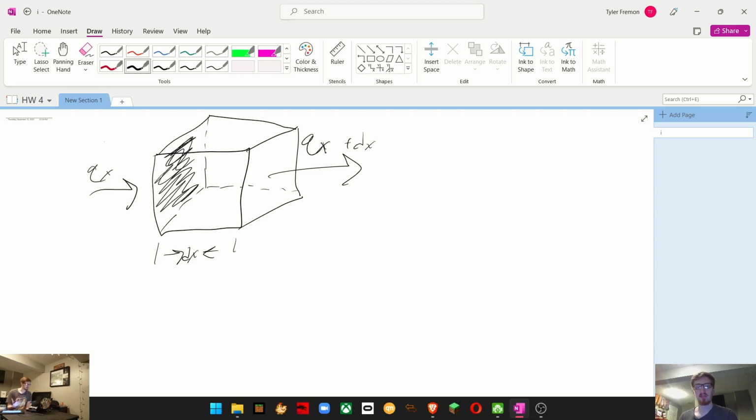And since our goal is to derive an expression for the overall heat diffusion and how we can plug in things that may change the temperature within the control volume, such as a reaction or energy being stored or removed, we can go ahead and just write an expression for qx plus dx and work from there.